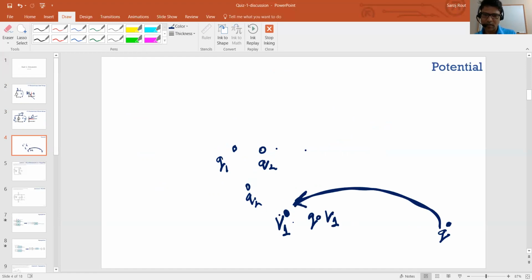But in a circuit, usually you never bring it from infinity. You usually go from one point to another, like from a point V1 to V2. So when I ask what is the potential of a point, that question is usually incomplete in a circuit, because your question should be with reference to what? If I say, what's the potential at V1, it should be with reference to what? Say I have a point V3 here. If I ask the potential of V1 with reference to V2, then that potential is V1 minus V2, right?